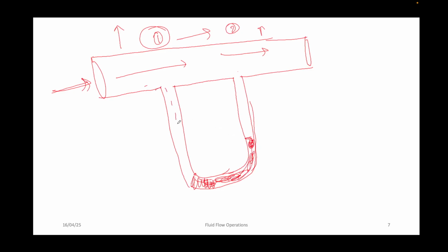Okay, so this will be filled with water or some fluid which is in the pipeline. So if you just take the difference of height, okay, this is the effective height, right? Effective height of, or let's say the difference between the height levels of limb 1 and limb 2. So if you just multiply with density and gravity, this will give us the pressure drop.